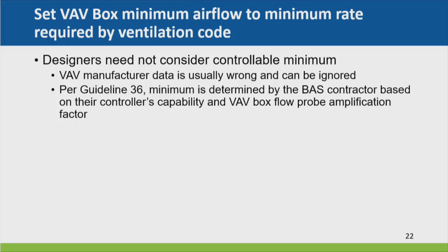All right, so set the box to the minimum ventilation rate. You don't have to worry. Don't even worry about that controllable minimum, by the way. Guideline 36 says, you know what? Since the manufacturers publish bogus numbers, and you as the designer,